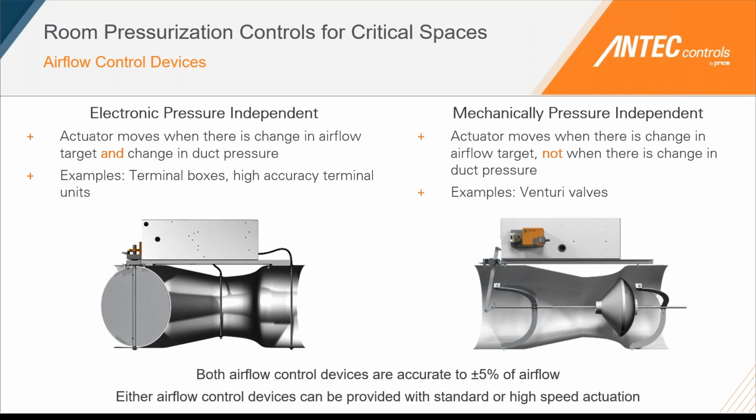Now, what we found in our experience is that the venturi valve design itself, if we're just talking about the valve, is actually very robust. So if it is operating in an application that it's designed for, so again, if it's a corrosive application where the valve is able to maintain whatever corrosive flow it's going through without corroding, the valve itself is robust in its ability to maintain a lifespan of 15 to 20 years.